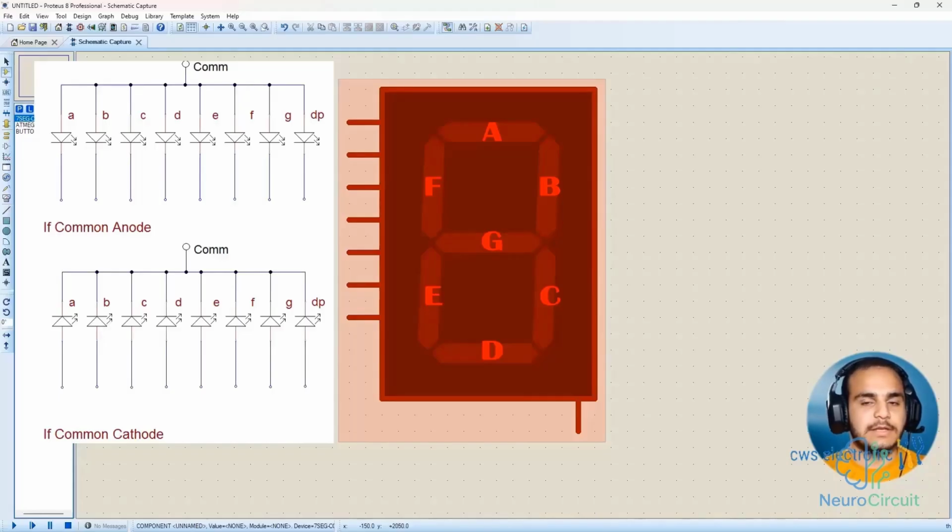So here we have 7 of those LEDs. Their negative sides are connected together and form a single pin. Their positive sides come out here so we can connect them to the microcontroller. And if we use or buy the common anode type from the market, it's the opposite, meaning the positive sides of the LEDs are connected together as a single pin, and their negative sides come out from this side to be connected to the microcontroller. So the system became very simple. From a distance, it might have seemed like a strange component, but it's really just this.